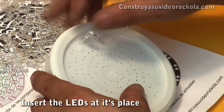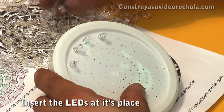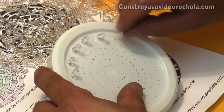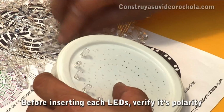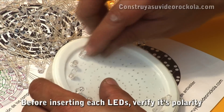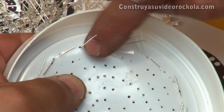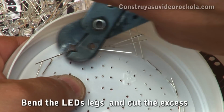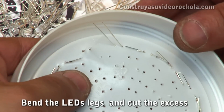Let's place them at the top, considering that all the LEDs stay with their negative pole facing the left side. In other words, the opposite of clockwise. To identify the polarity of the LED, we know that the short leg is negative. If by mistake an LED is placed upside down, the circuit will not start. We bend the legs of the LEDs and cut them to sufficient size so that the positive leg of each LED is followed immediately by the negative leg of the next.